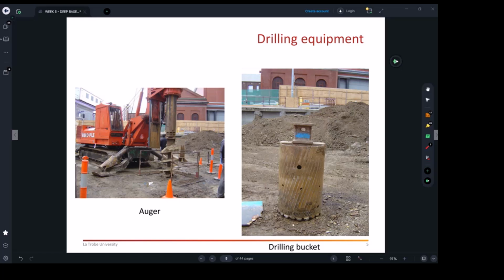As I said to you in other topics, sometimes we have fill. Fill is just a very loose material, which is very difficult to work with. Whenever you excavate that meter, or 1 or 2 meters or 1.5, it's going to collapse again and again and again, and you can't really progress. So what we do in such a condition, and remember, you're going to be having a decent soil report.